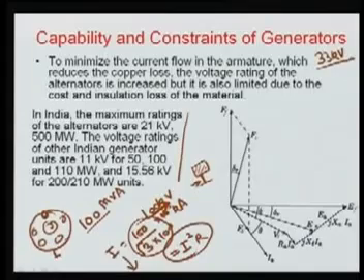The main problem here is that we cannot increase the voltage excessively beyond this, because at this corner you can see there will be more field. This stress on the dielectric, this E field, will be higher at the corner. If there is any sharp corner, there will be more. So there will be a possibility of hot spots, and also more eddy current and more losses here, and there will be some problem here.